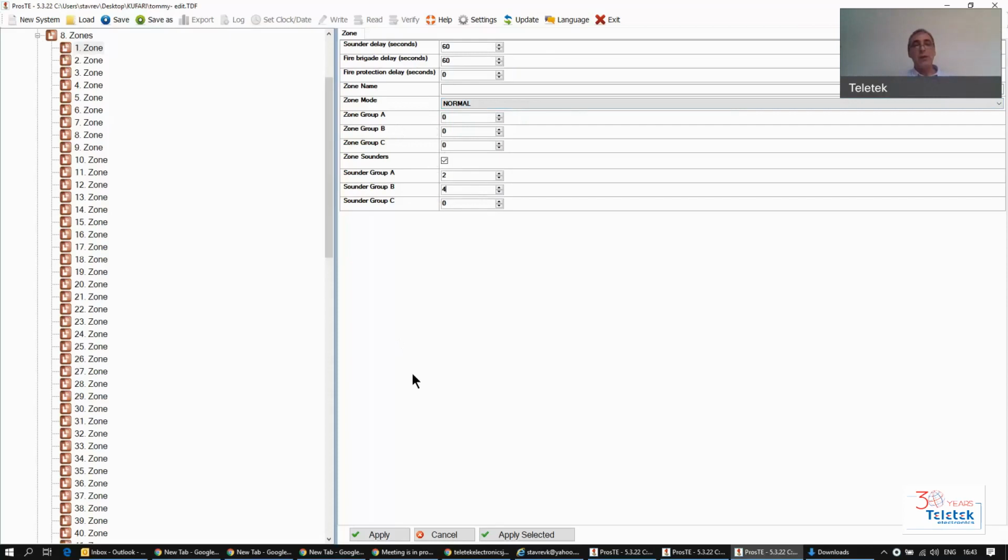So I guess with this we'll end the mystery about the zone settings. One thing that comes to my mind that is applicable for detectors, zones, devices, and other things is called cloning. Imagine I need all my zones to be with mode double. The long way: I go through every one of them and set up zone mode double, or the delays, or which groups they belong to. Regardless, I'm going to use just the double option here to visualize and explain how cloning works.